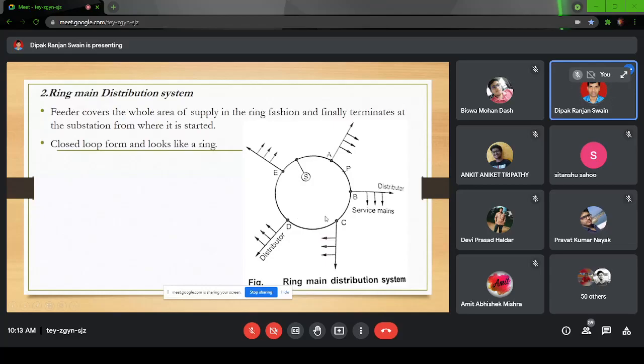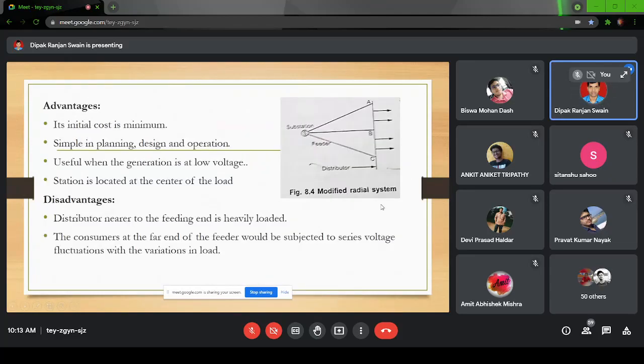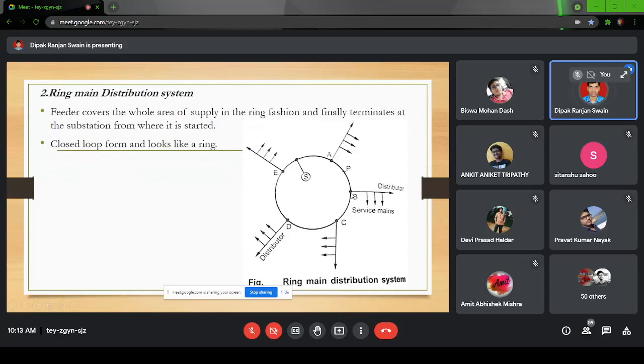And as it is going to be stabilized by a ring system, let us say there is a low voltage here, so the current will flow from the other side to stabilize it. Similarly, if there is a low voltage at the point P, because at that tapping, let us say the load demand has increased suddenly. In a particular area there is development and load demand increases suddenly. So what will happen? At point B, there will be a heavy demand of current. It has two paths. Some part of that current will come through A, some part of that current will come through EDC, so that there will not be much voltage drop in only this line. It will be equally distributed in all the feeders.